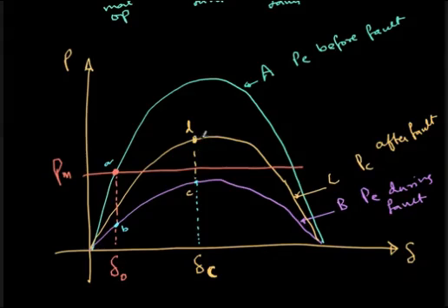So here, electrical power is more than the mechanical power. So the rotor starts decelerating. But still the rotor will overshoot because so far it has been accelerating. The area representing the acceleration is this one. From this point onwards, the rotor starts decelerating and it can achieve maximum area up to this point or earlier.